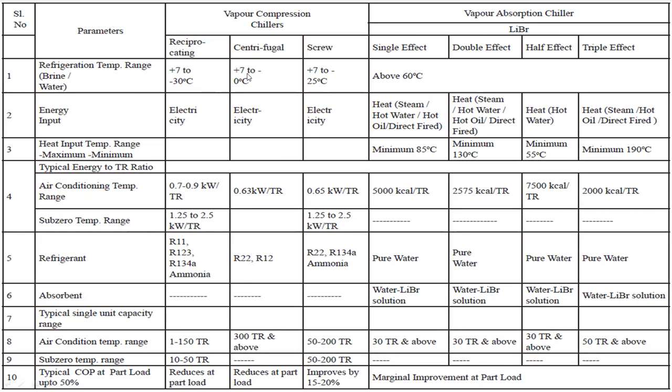For centrifugal, +7 to 0 degrees centigrade. For screw compressors, +7 to 25 degrees centigrade. For vapor absorption, for all effects, it is above 60 degrees centigrade. That's the refrigeration temperature that will be maintained.